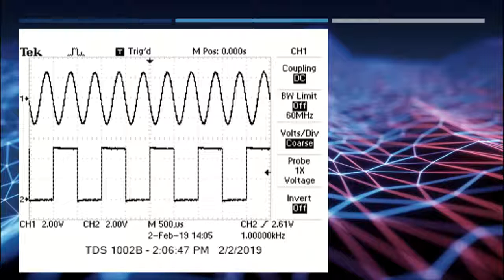And so we've successfully shown that we can input 2 signals into our oscilloscope in channel 1 and channel 2. We can display both of those signals on the screen at the same time, and we also know how to analyze them. We have a separate volts per division for each channel. However, the time per division scale is the same for both, and we can see that on our screen. We have successfully done this, and we have learned a lot about using our oscilloscope.